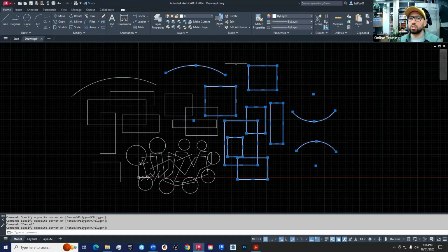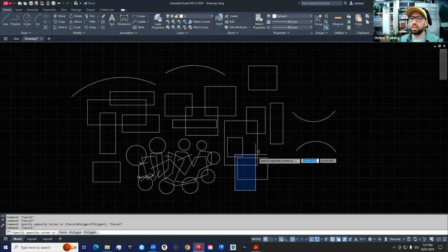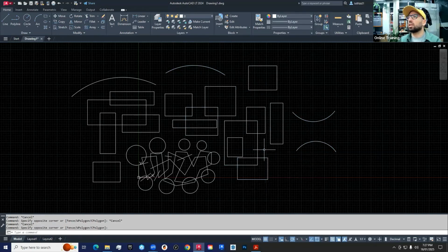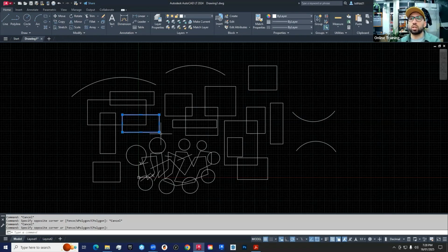What if it's a blue selection? If you do it from left to right, either the top left or the bottom left, and you intersect with an object, it doesn't select it. You need to cover the whole object in order to select it. So green, intersect with even a millimeter of the object, it selects the whole thing. Blue, you need to cover the whole thing. Okay. So you just make a blue selection and just highlight this one. And it could be more than one. In more cases, it's going to make much more sense later on.